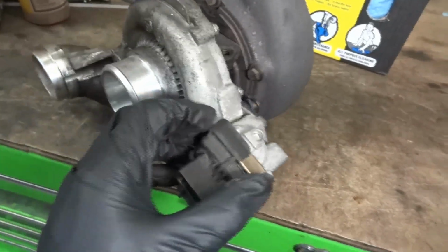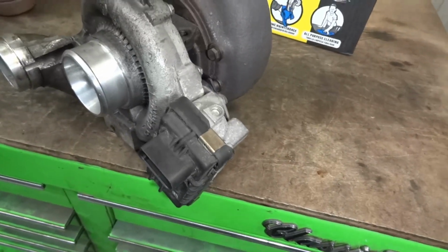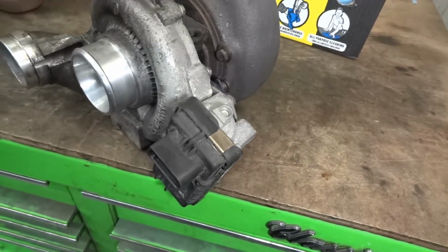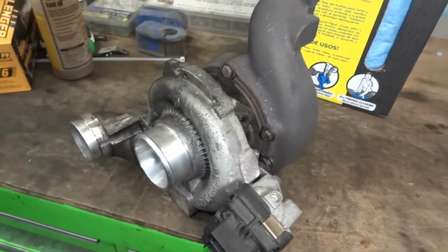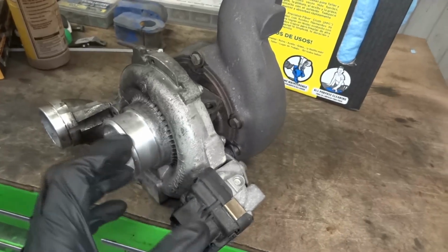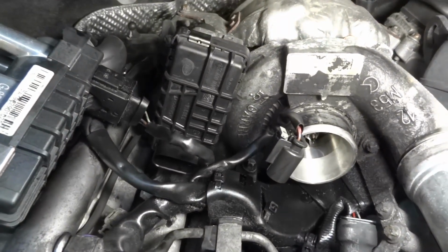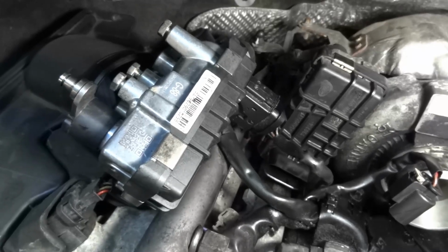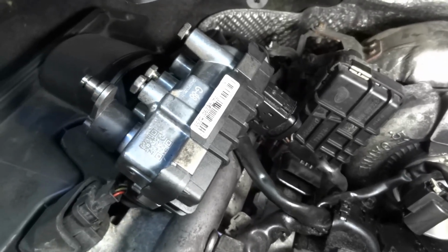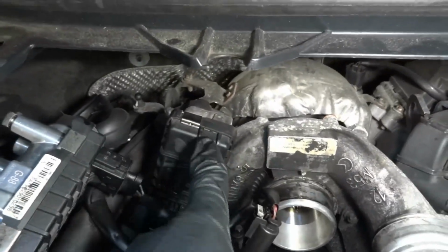So I'm gonna remove this. We're gonna connect it to see if this one is gonna make that clicking sound also. If it doesn't make the clicking sound, we will be 100% sure that the actuator on the turbo on the vehicle is bad, okay? So I'm gonna get this out off camera and then I'll bring you guys back up. So I disconnected the actuator on the turbo. I got the electrical connector of this actuator connected to this one. We're doing this to see if this one is gonna make that clicking noise also. If it doesn't, then we will know for sure that this guy is bad.